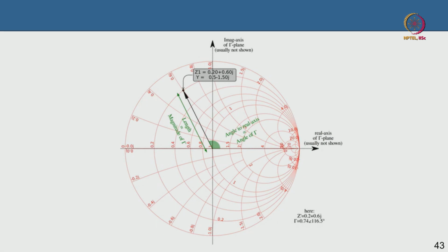That concept is adding a transmission line. Suppose I have a transmission line of length L. If I add a transmission line to, say, a transistor or a load, what does the transmission line do? You will see that the transmission line does not change the magnitude of the reflection coefficient. The transmission line introduces a shift in the phase, we will see that. Before that, just for example, I will come to that, this is part of that only.